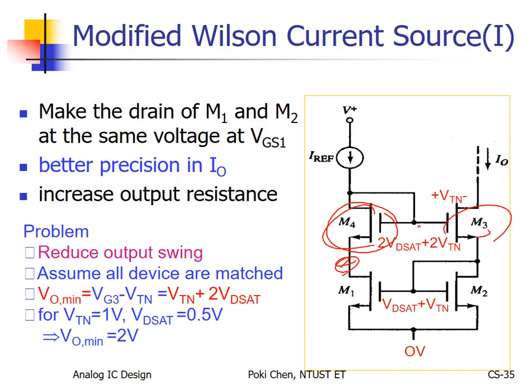So my voltage needs to be here, 1 VTH and 1 delta V lower. Exactly the same as there, right? So the major help from M4 is to make the drain voltage of M1 exactly the same as the drain voltage of M2. That's it. To balance the conditions for both M1 and M2.